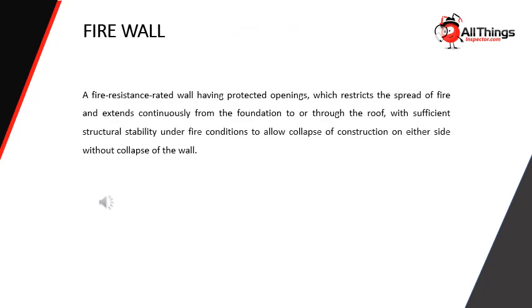Firewall. A fire resistance rated wall having protected openings, which restricts the spread of fire and extends continuously from the foundation to or through the roof, with sufficient structural stability under fire conditions to allow collapse of construction on either side without collapse of the wall.